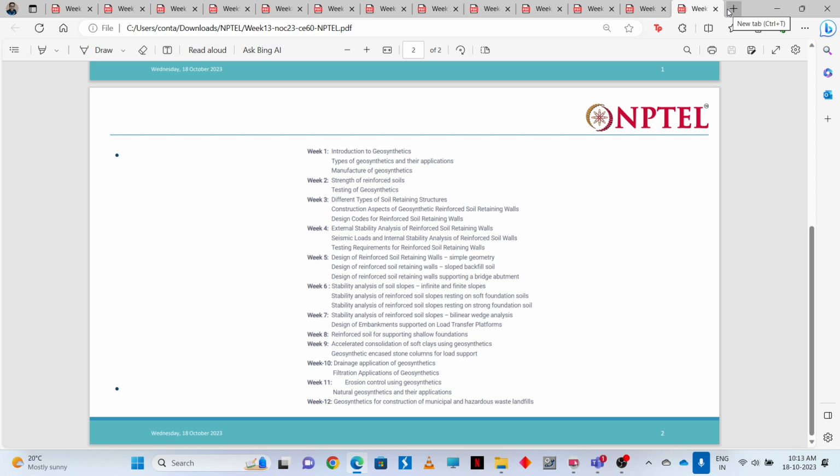Then unsaturated soil mechanics also comes into play. In basic soil mechanics, whenever we solve the problem, we solve it in such a way that the soil is completely saturated. So rain will come, soil will be saturated. But actually, soil might not be completely saturated, so unsaturated soil mechanics come into play. We need to model this with the help of certain complex software. These commercial packages have included all these concepts, and with the help of that, we can design them.